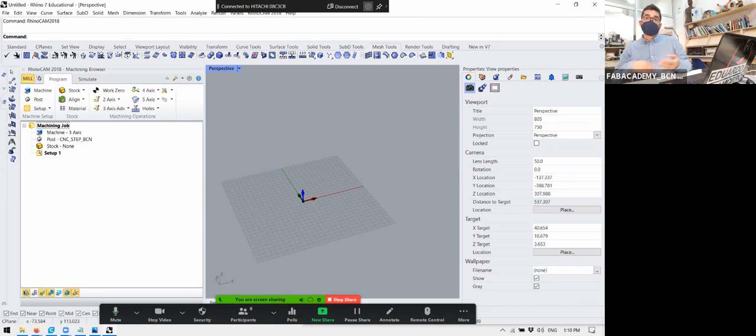The same happens with the software. The slicers for 3D printing are millions, and sometimes, like with Cura, which I've been using since version 2, I think, they update, there is a bug, and suddenly that version doesn't work or produces a glitch in some cases. A glitch in a 3D printer, you don't care. A glitch in a CNC usually means a broken end mill. And if you're cutting carbon fiber, a broken end mill at really high speed is something you don't want to happen. So that's one of the reasons why I think most CNC interfaces look like 90s style, because they don't update things. In general, for fabrication, updating unless you need to is the last thing you want to do.